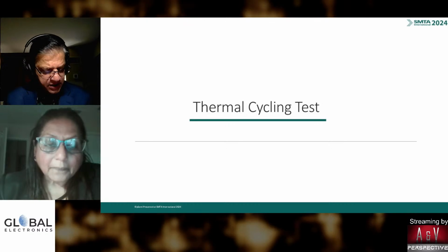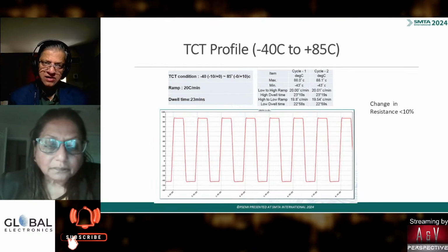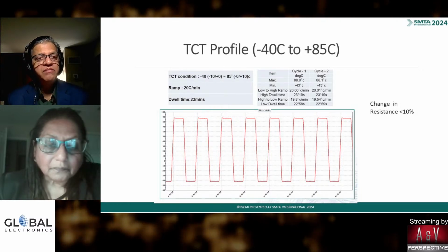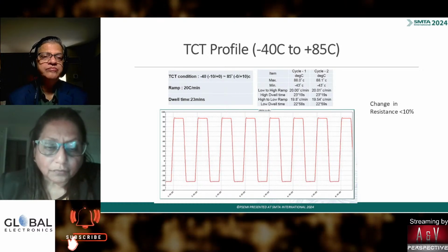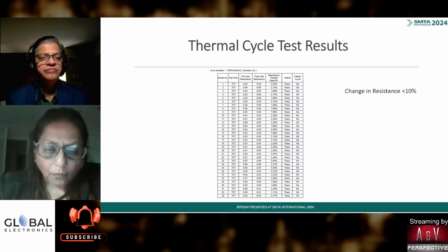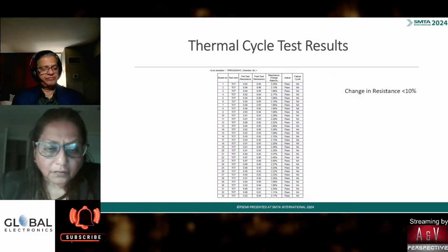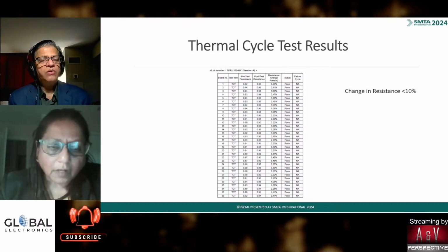I know that you mentioned JEDEC standards. Does IPC have certain standards on board level reliability tests? So yes, IPC has the 9701 series of standards. They are for board level reliability. They are for monotonic bend, mechanical shock. Several standards have already come out for board level reliability.